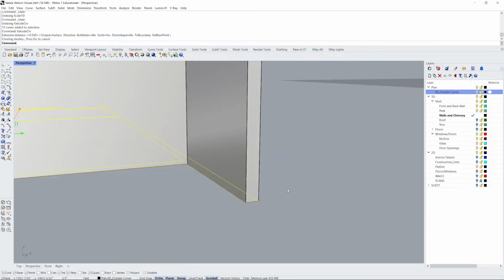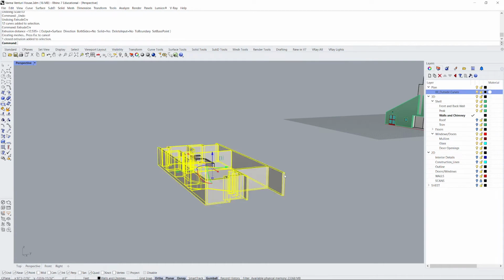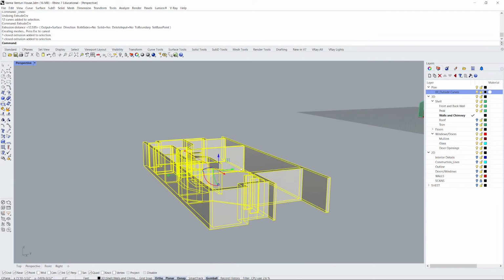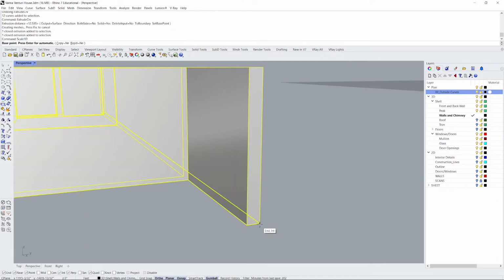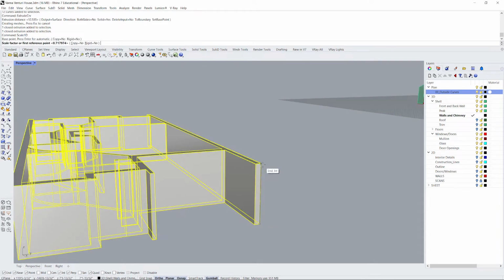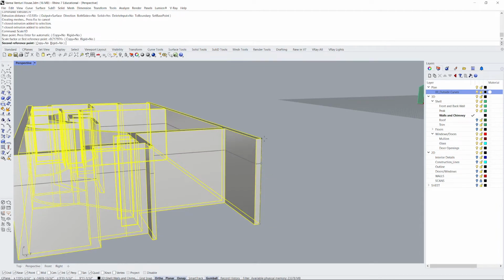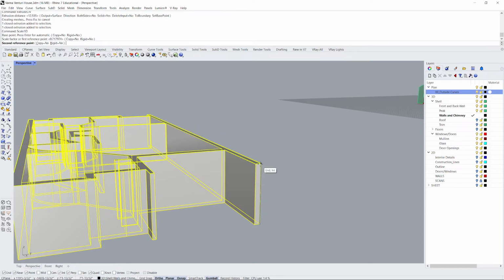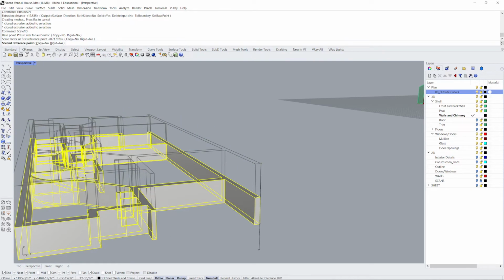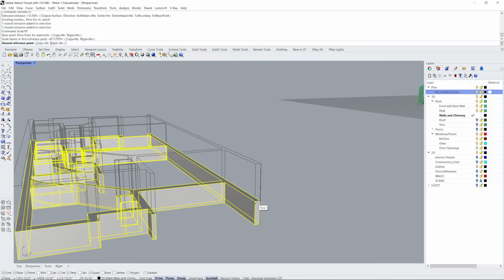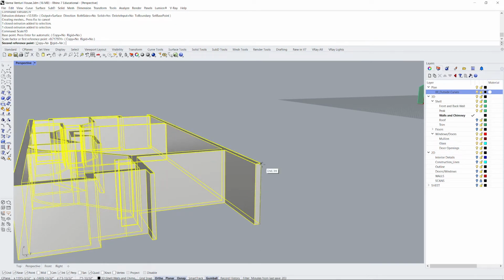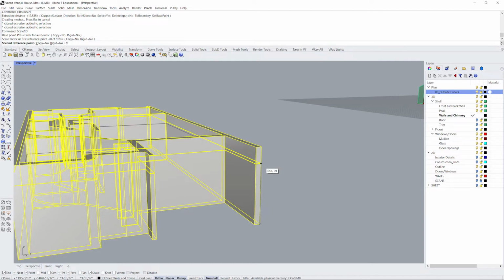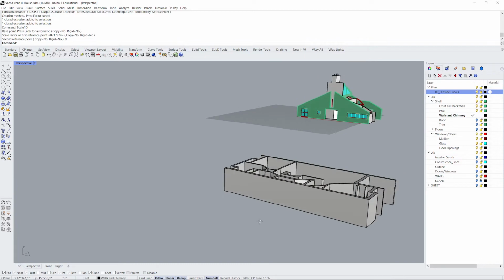So I don't actually know what that distance ended up being. So if you ended up where you're not quite confident in what that height of your extrusion is, you can also use the scale 1D command. And now you just select a base point, which would most likely be the ground, and then the top of that wall. And when your mouse is hovering over something, if you look down here where my mouse is, it says the current height. So that says 7'1" something. So that shouldn't be right. So I'll just type in 9 feet and we'll experiment with it.